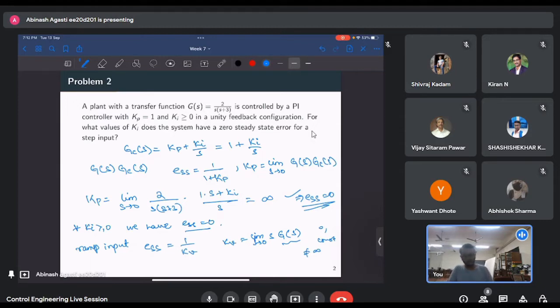Okay. So in general, the more integrators we add to the system, the more we guarantee that the steady state error will be 0 for different kinds of input. If you have a simple step input, then only a single integrator in the open loop transfer function will get us to 0 steady state error. If you want to track a unit ramp, then 2 integrators will help us get to 0 steady state error.